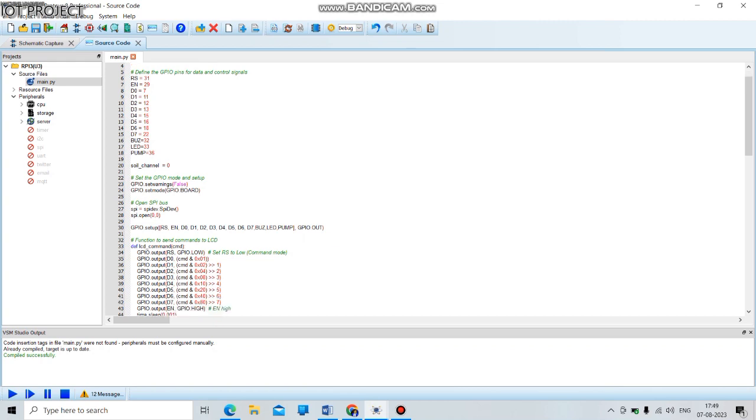Okay, now come to this line. For removing unwanted warnings, I have to use this function where False is taken as an argument. GPIO.BOARD means that I am using the pin numbering according to the physical pin numbers of the Raspberry Pi, so I have to use GPIO.BOARD as an argument. If I want to use the GPIO numbering, like GPIO 17, GPIO 7, then I have to use GPIO.BCM as an argument. But I am not using that, so I use the GPIO.BOARD function.